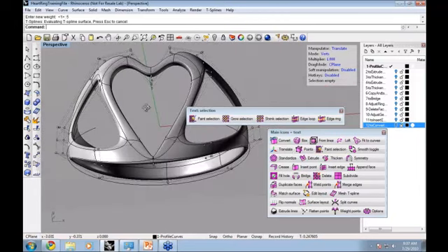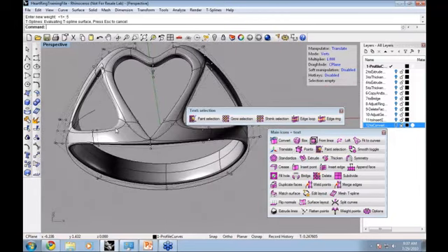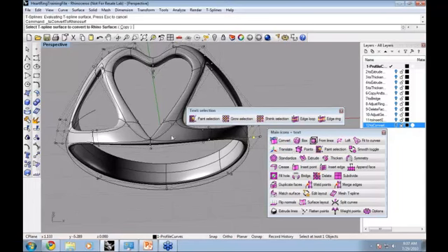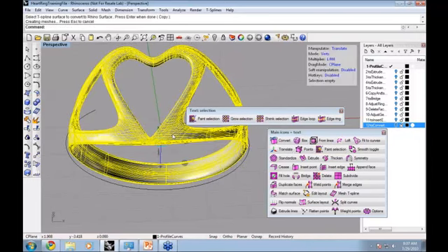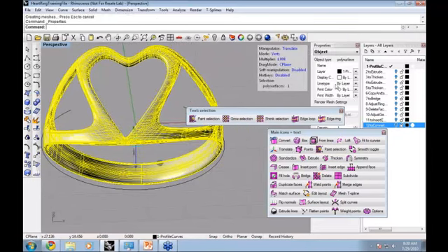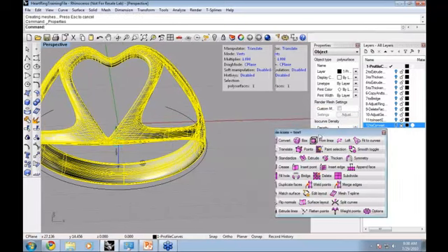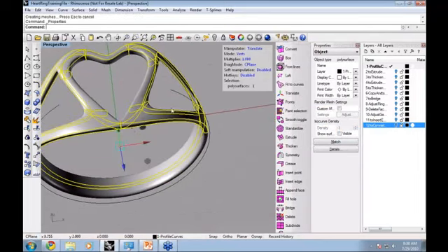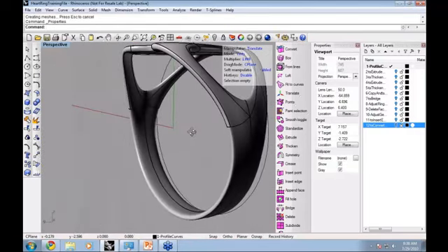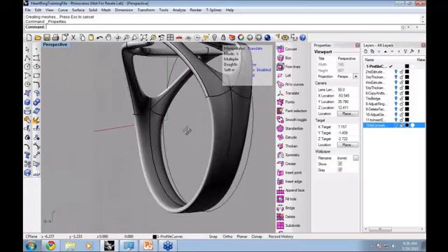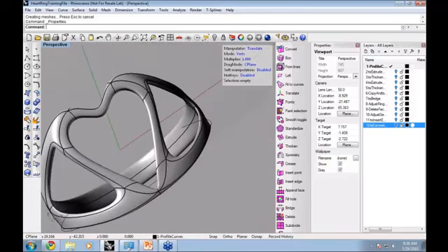But now that we're done with the T-splines design, going to Rhino is just a push-button conversion. We can just use this convert button, and I'll right-click it to convert to Rhino surfaces. Let me hit F3 so we can show how the surface layout is here. Now the T-spline is just split up into Rhino surfaces, and so you can use any of your Rhino commands on this T-spline model now.